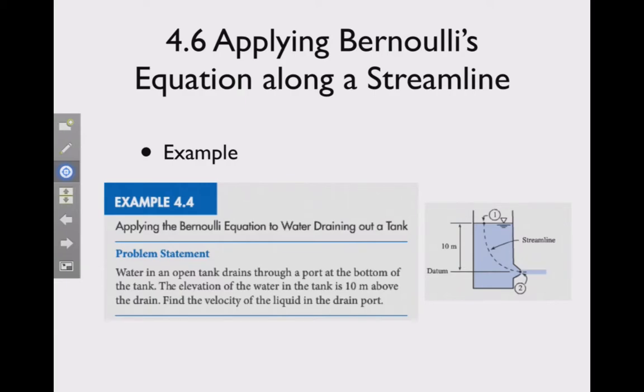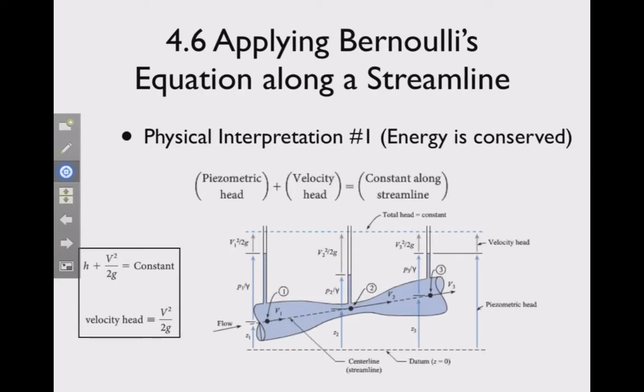So this is a very convenient way to look at moving fluid in some sort of a pipe. As long as we identify an appropriate streamline, and usually the best way to do this is to choose the center line of a pipe, then we can realize that the total head or the total pressure is going to remain constant throughout the entire flow, as long as we're on a streamline.